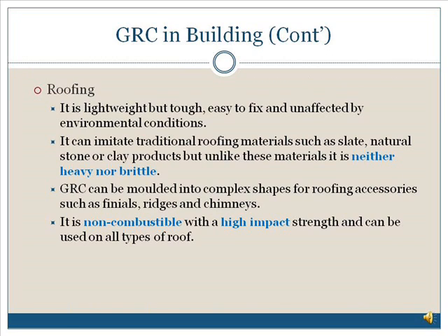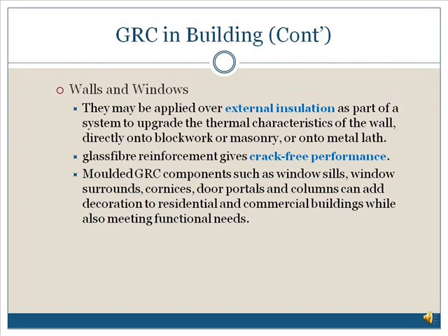GRC in buildings is very popular in roofing because it's very light and not brittle, unlike other alternatives such as slate and natural stone or clay products. It's also non-combustible and has very high impact resistance. GRC in buildings also includes working with walls and windows. It is used for external insulation, and it provides a crack-free performance.